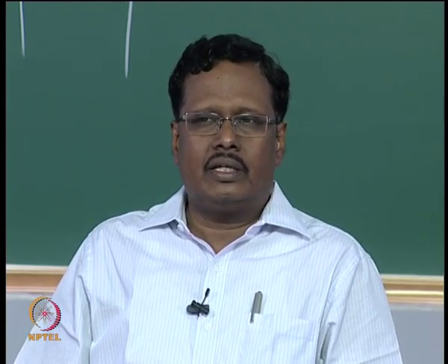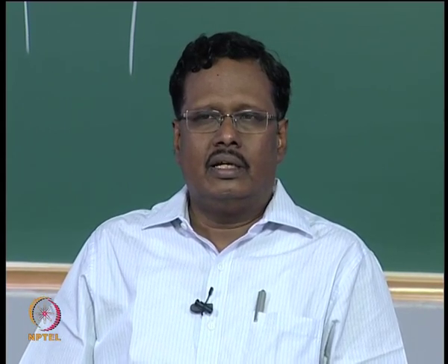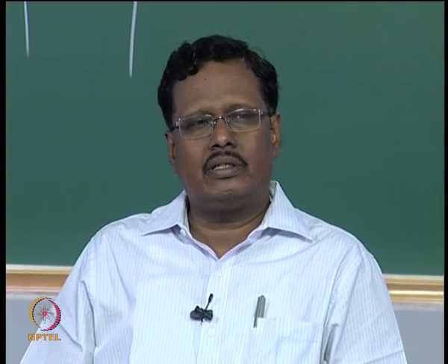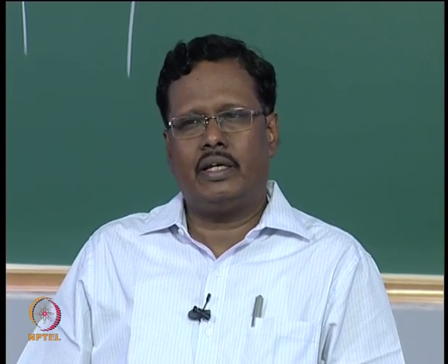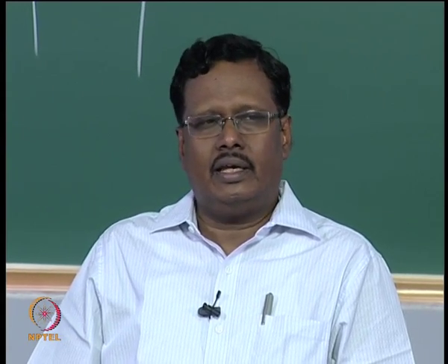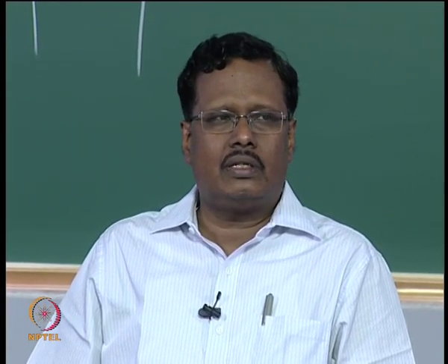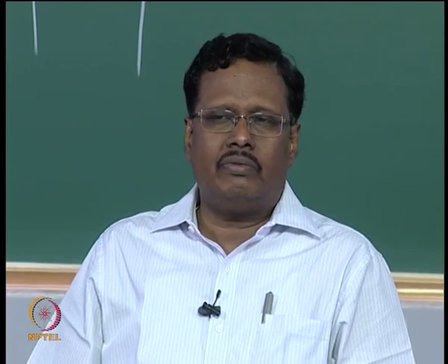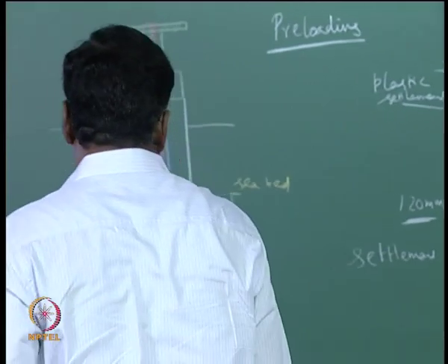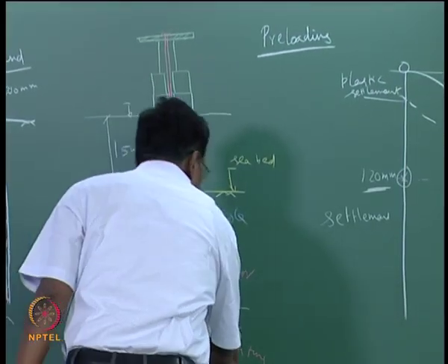See, the pile load test, this is the final thing which you should remember. It is not the load that the pile can carry, it is the load which it can carry with permissible settlement. We have two types of settlement, one called permanent, or total, settlement, and another called differential settlement.